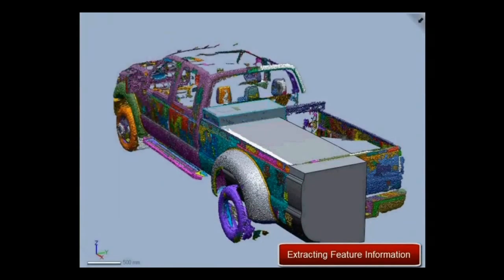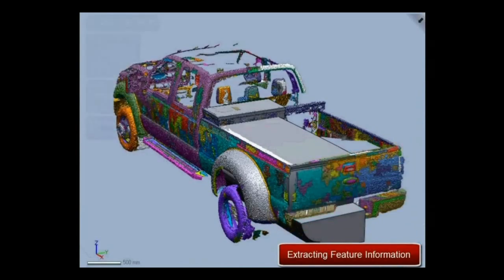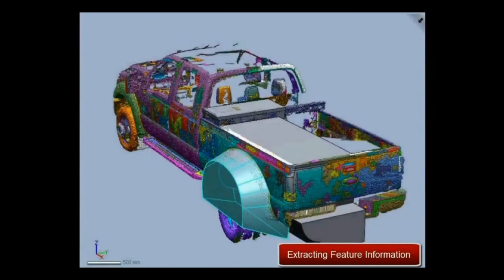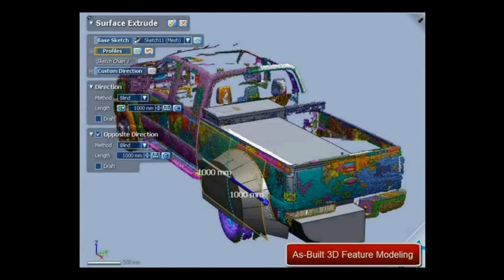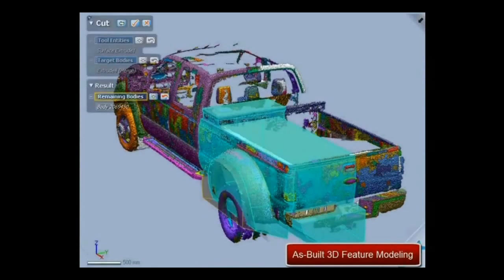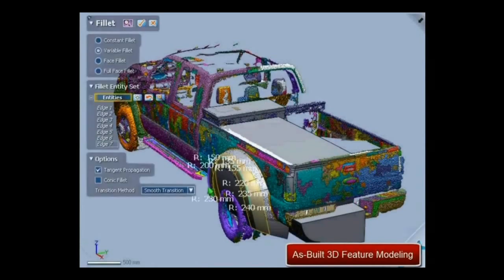And Rapidform is capable of combining both modeling variants. So you can cut a solid by a surface, or you can create a closed surface set, and each closed surface set is considered a solid body. Or you can delete one face from a solid body and then you have an open surface set, so you can go back and forth.